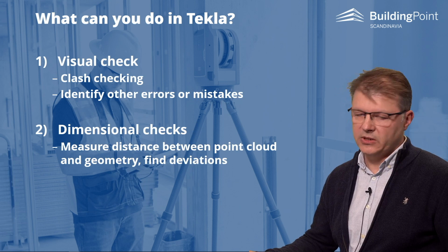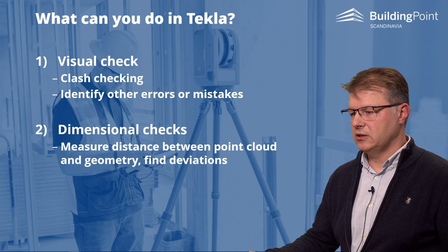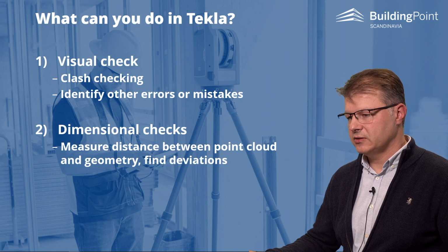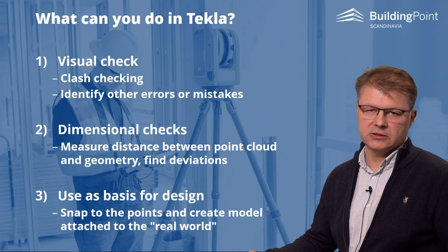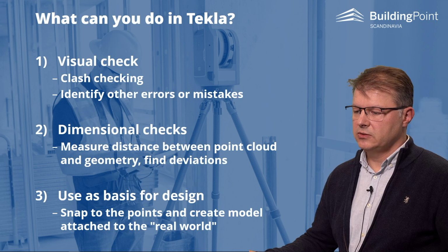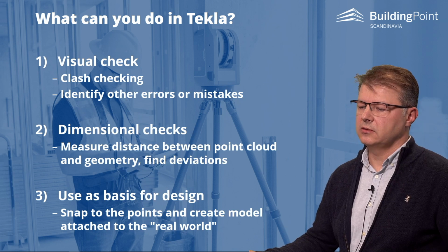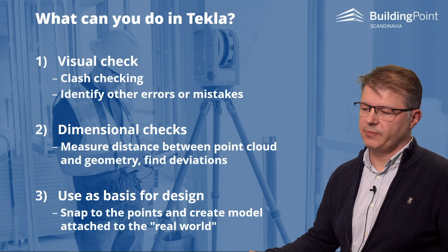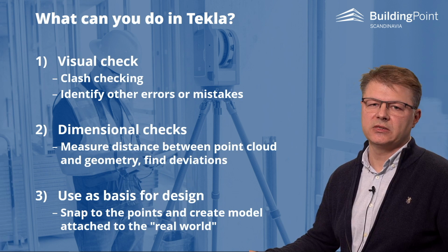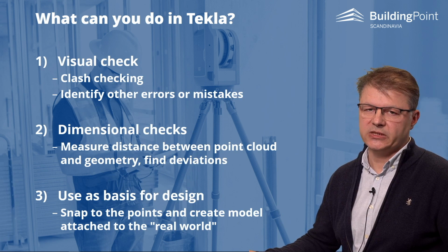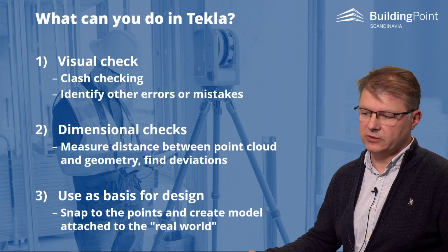You can measure distance between the points and the different point clouds, and you can check the deviations. You can also use the point cloud as a basis for design. You can just click on those points and create, for example, Tekla objects based on points from the point cloud.